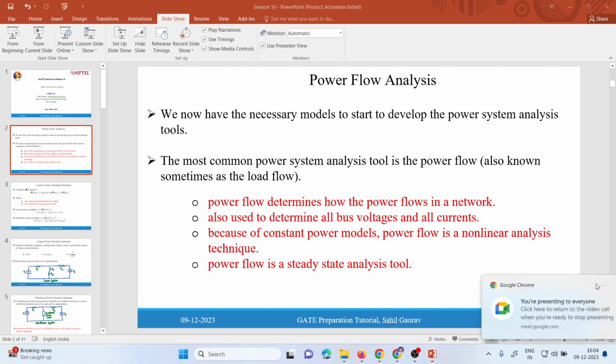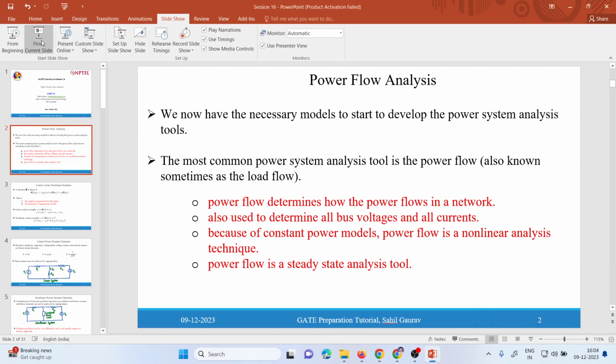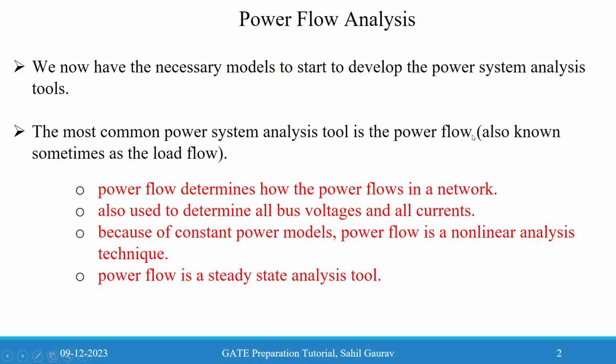And the most common power system analysis tool is the power flow, that is also known sometimes as the load flow. And what are the benefits of this power flow and what is the significance of this power flow? Power flow determines how the power flows in a network, and it is also used to determine all bus voltages and all currents.